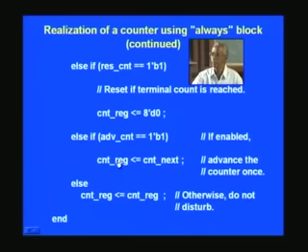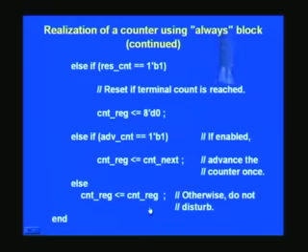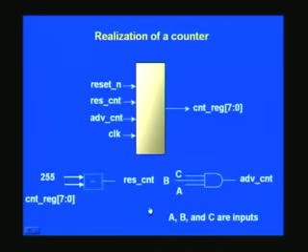Another alternative way was to dispense with that assign statement there, and thereby remove one signal. We are unnecessarily introducing one signal, but with the aim of increasing the speed of processing. So that's a good habit. And here we could have put the same counter reg plus 1 right here, that also will work, but what is happening is that only when the clock strikes does it start computing, right. So with this, if this is not satisfied, we will not disturb the contents of the counter register. So are we clear about the whole thing?